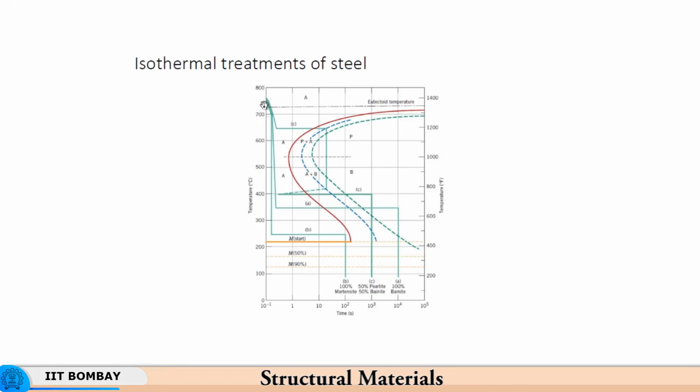Now, if you take a very high cooling rate, and you always miss the transformation curve. So, this is the curve describing the initiation of transformation, right. So, you do not want it to transform, you hold it for a while and then you quench it further, you instantaneously cool down to the martensite finish temperature, then you will have 100% martensite.